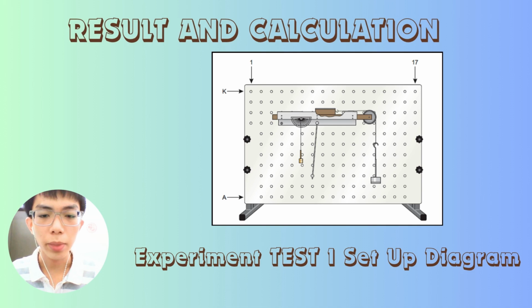This is the experiment setup diagram. First, we place a friction block on the trigonometry table. We adjust the angle of inclination of the trigonometry table. When the friction block starts to move, the angle on the protractor is recorded. Tan of the angle on the protractor is equal to the coefficient of friction.